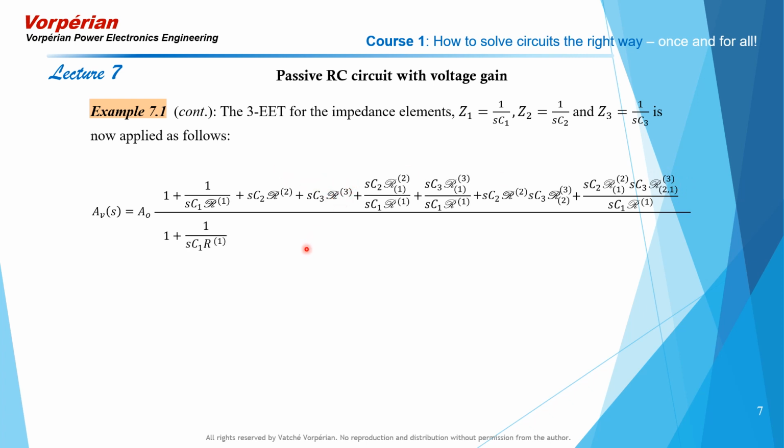We repeat the same thing in the denominator, except all these port resistances looking back into the network are computed with the excitation set equal to 0. So each impedance element comes in one at a time, and the resistances are the driving point resistances looking into the network from the ports where these elements are connected, with the excitation set equal to 0.